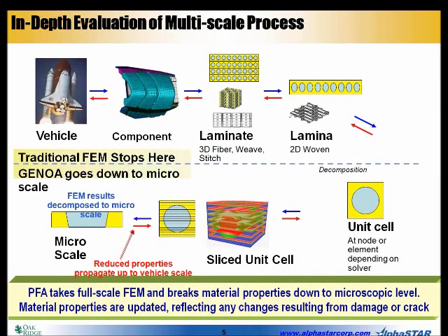The philosophy that we are using is the multiscale analysis methodology, where we extend the current capabilities of classical and commercial finite element tools by including micromechanical material modeling, where we have a unit cell of the micromechanical structure, in this case a composite.